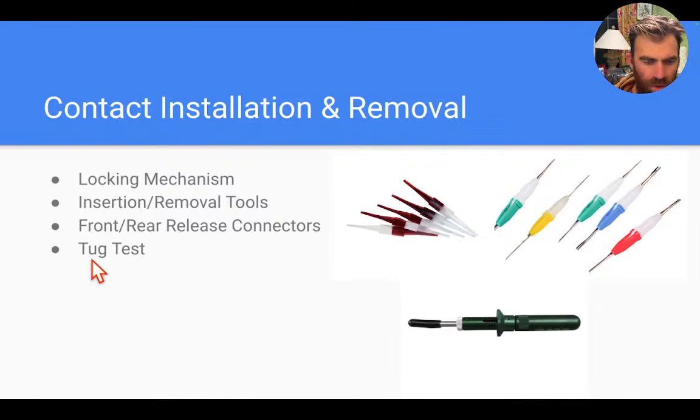And then one last important note about installing the contacts into the connectors is that you can do a tug test. So you would insert the contact into the connector itself, and then you would just pull a tiny bit to make sure that the contact is seated into the connector itself.